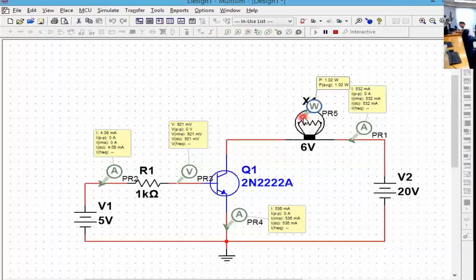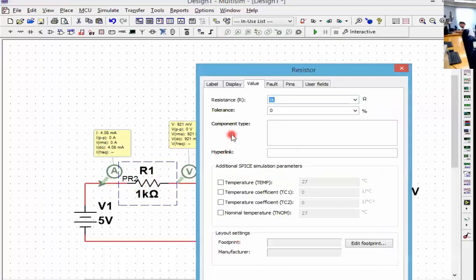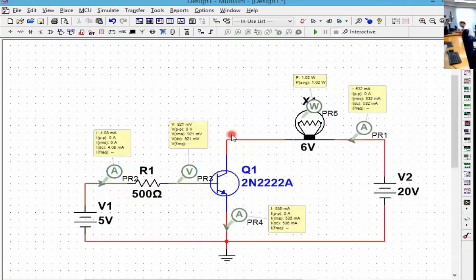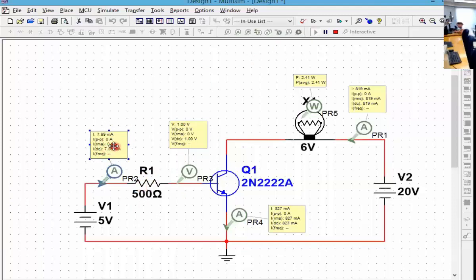So it should, yeah, I think it doesn't show it, but the current is not enough definitely to use it. But let me lower this to see. That's why usually on the base side for testing we put a potentiometer, so that we don't need to replace these resistors every time. See that as soon as I lower it, you see the current increased on the base. Of course, the base current increases, collector current increases. The voltage on the base was increased slightly.